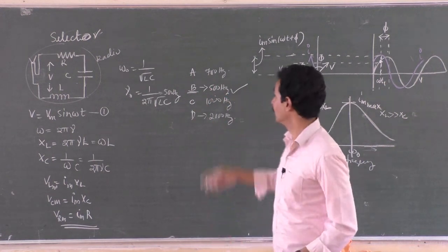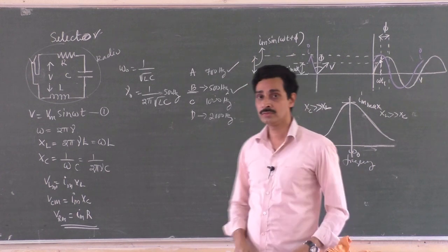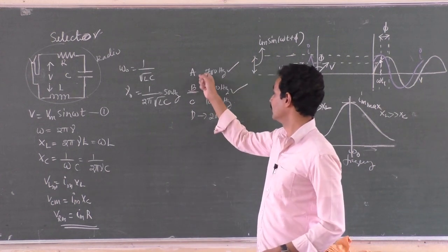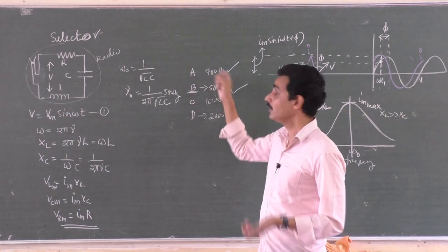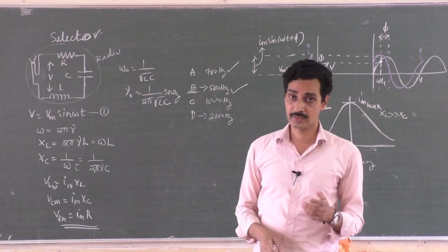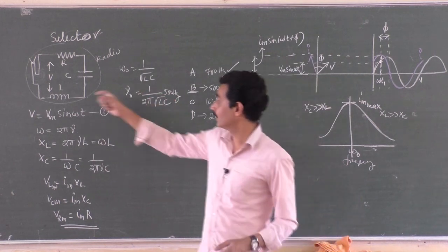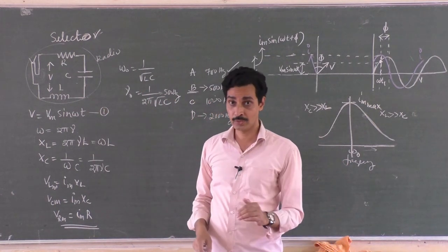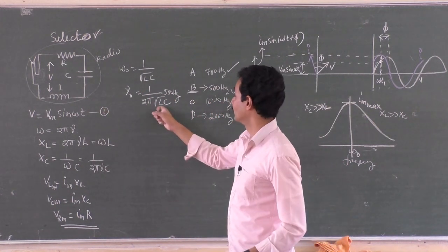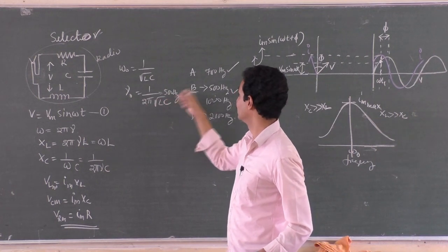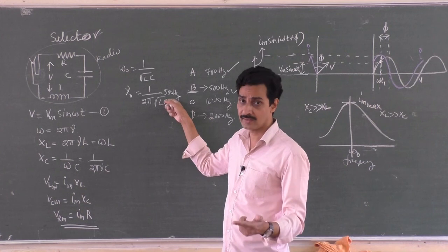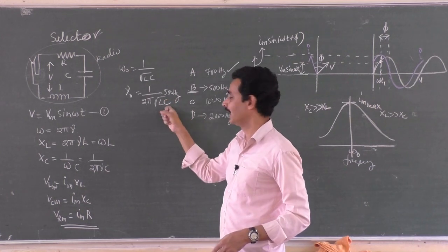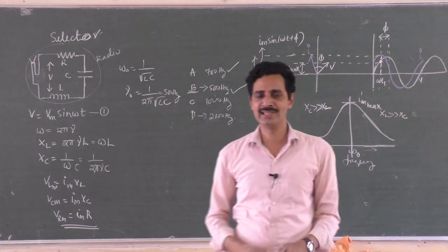Sir, I want to hear station A. What do I have to do? I have to change the resonant frequency of that circuit. So if I want to change the resonant frequency, you have to set an RLC circuit inside that radio which, when I substitute L and C, gives an answer exactly equal to 700 hertz. But it is not giving 700 hertz now, it is giving 500 hertz. So what to do? Change either L or C. That is what you are changing in the radio.